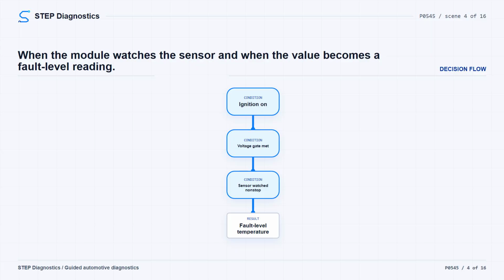As a quick data clue, the scan data matrix shows a signal short to ground at -40 degrees Celsius, -40 Fahrenheit, while an open signal, short to voltage, or low reference fault can show 1000 degrees Celsius, 1832 Fahrenheit. After a cold start, the exhaust temperature sensor value should rise steadily and then stabilize.